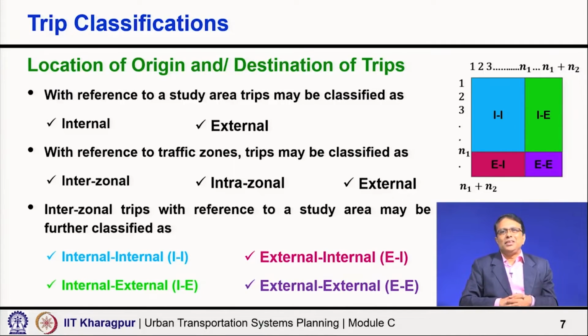As I said in some other context earlier, that is the typical segment we should consider if we are thinking of a bypass for a town. If that external-external is significant, it means these trips are all captured at external cordons. Why? Because the road passes through the city, but the traffic has nothing to do with the city.